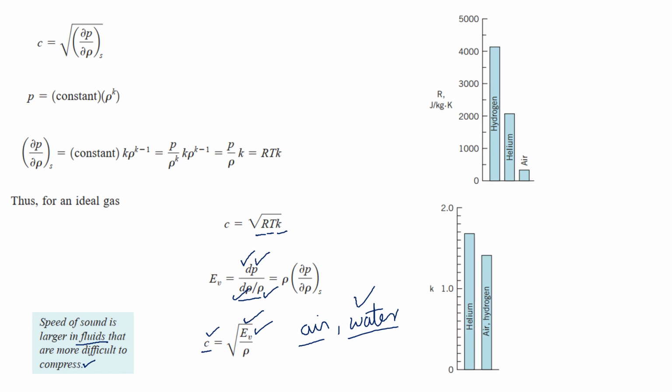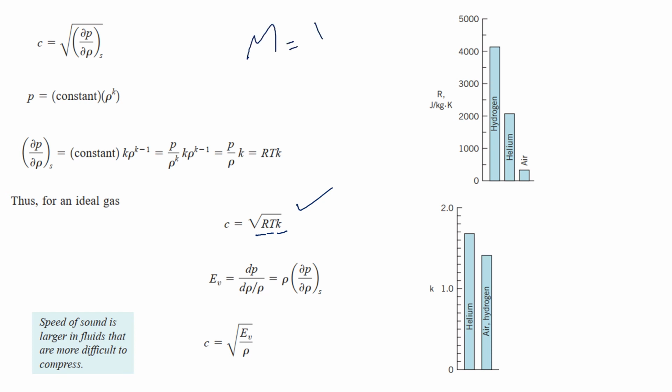So these are the equations that are related to the speed of sound. They give you the same thing, the speed of sound, but they can be used in different scenarios. For example, these equations can be used for different gases having different temperatures and specific heat ratios, and this equation can be used for different types of fluids having different values of compressibility. So this was related to the speed of sound that we had in our Mach number, that is the velocity of the object over the speed of sound. And the Mach number, as we already said, tells us about the compressibility of a certain fluid.